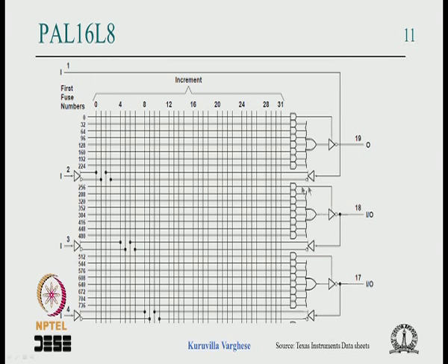So it can be output, it can be input, it can be IO, but instead of thinking of it as a separate thing like output or input, you can view it as this output coming back to this whole logic, okay. So it shows that this as a node can be used along with the other product terms. The use is that suppose you have a boolean function with say 10 product terms, then we are not able to implement that here because there are only 7 product terms.